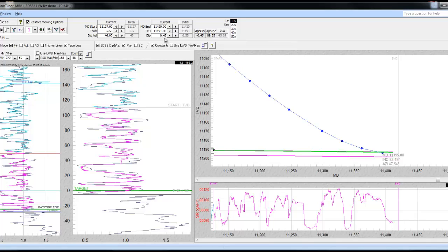So at 0.45 degrees, the bed is dipping in a northerly direction, so it's subtracting the inclination from 90 and giving you 89.55 degrees as the drilling inclination. It also gives the apparent bed dip here as well, which is negative, which simply means, of course, that it's dipping down, therefore it's negative to the north. That's briefly the param tuner screen.